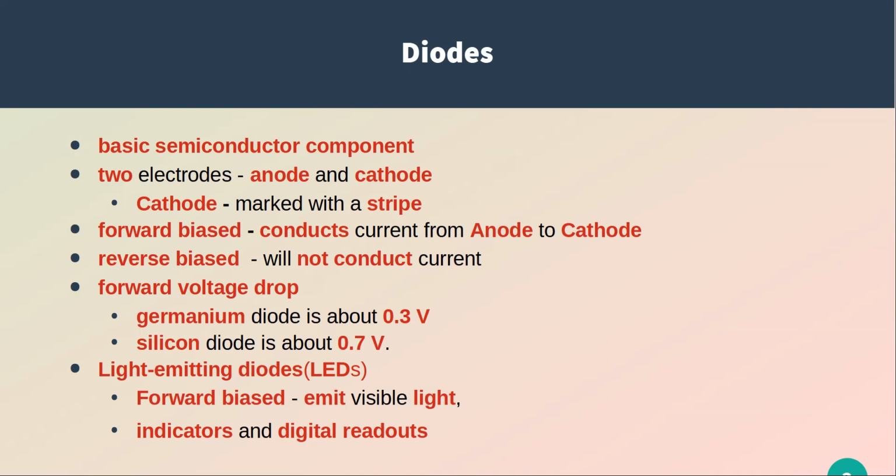attract the electrons and flow in that direction, and only from cathode to plate. Semiconductor diodes work the same way. They only flow in conventional current from the anode to the cathode. Electrons are actually going the other way, but we're going to talk about conventional current flow, which was defined backwards way back when Benjamin Franklin did it. So we're stuck with it. And it's actually the way holes flow when we talk about semiconductors.